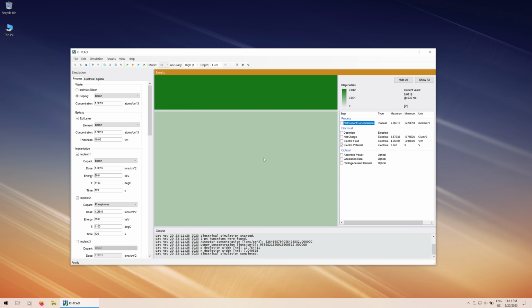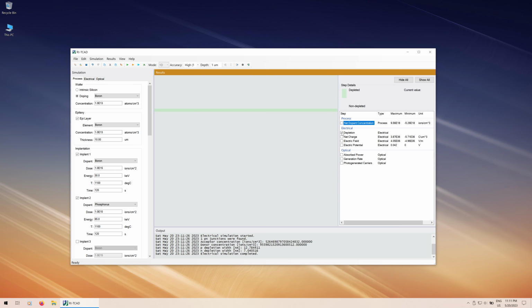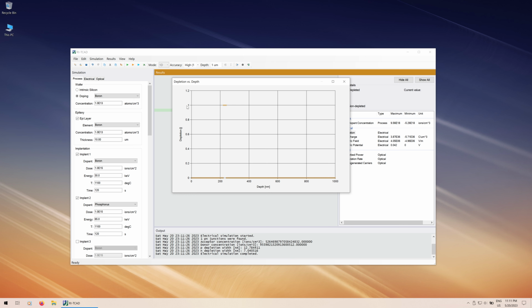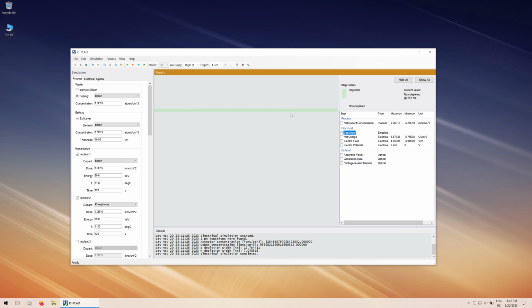We've got some electrical potential calculated, again, versus the depth in the silicon. Let's quickly take a look at the depletion, how it looks. Okay, so that green tiny sliver is the depletion. If I plot this, you see on the plot, the region where it says 1 means that the material is depleted. So again, around our junction, a very narrow, very tiny depletion region, a very small space charge zone, which will have some impact on the performance of the device, you will see.